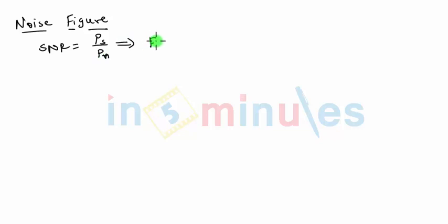The next parameter, which is frequently used in the representation or the measurement of noise, is called noise figure. Now noise figure is closely related to SNR. We have defined SNR as the signal to noise ratio, PS by PN. We went on to define noise factor in case of an amplifier or any system which adds noise to the input signal.